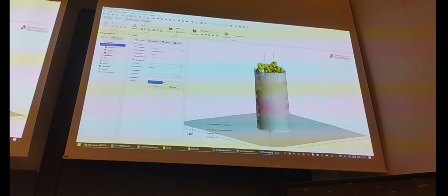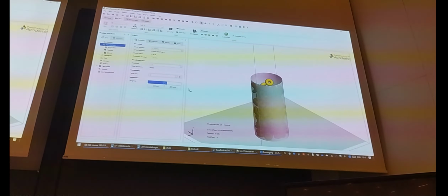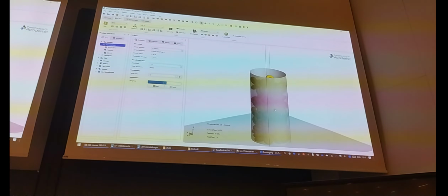So change to donuts. So start with spheres. Find out the critical time step. So okay, let's drop the sphere on the bottom and it's stable. Everything good. Increase the time step a little. Unstable, catastrophic. So make a Newton's approximation and find the stable time step. So I decreased it, and 0.05 works like a charm. So particles are in there, they're moving a little, but that's it.